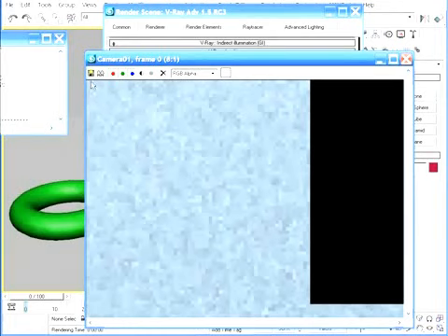Now I'm going to count the number of dots that I see across in each bucket. When I do, I can count that there are 64 dots across and 64 dots top to bottom. What does that mean? Well, that means that for every pixel in the final render output, there is a dot. And that means that my Radiance map is the same resolution as the final rendered output.